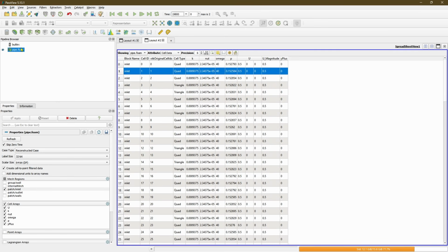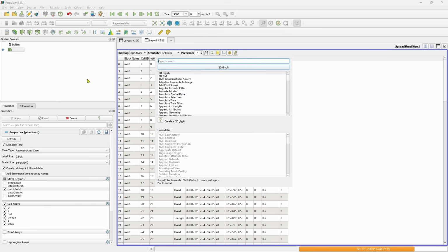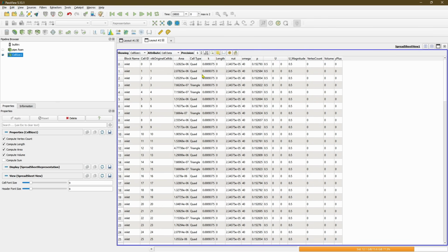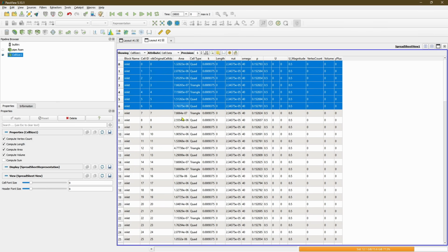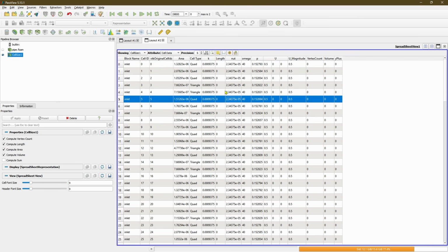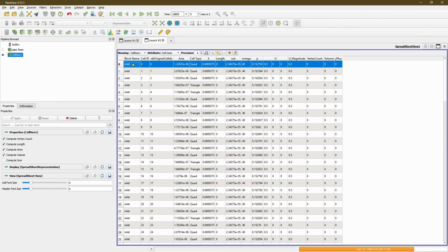Now what we would want to do is control space and just do cell size, hit enter, hit apply. So with the cell size, we will get the area and we will get the pressure values. What we have done is export this data in the spreadsheet.